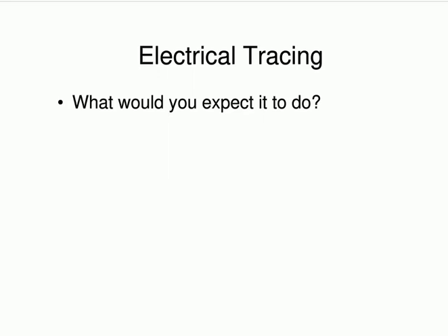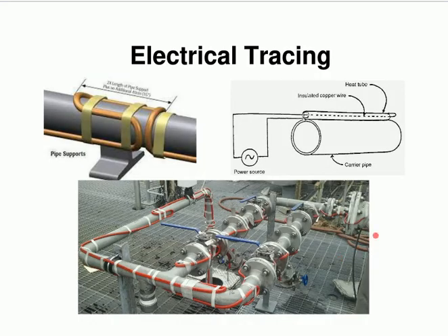A conductor to heat the pipeline, pretty much, yeah. That's pretty much all it is. You get some heat wire, so it has a small resistance, and when you put something like 240 volts across it, the small resistance will generate heat. Let me show you what it looks like. But yeah, spot on, Sam and Luke from Tutbury. That's what it is, okay?